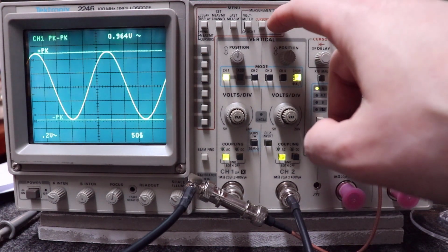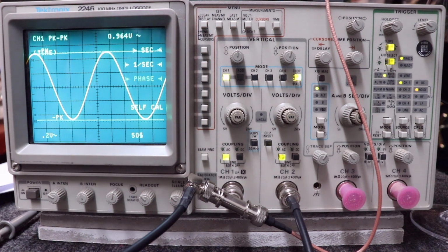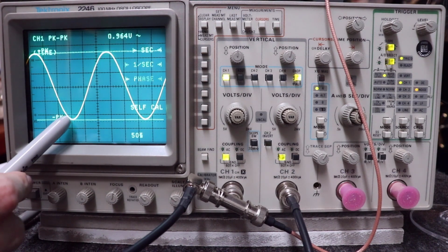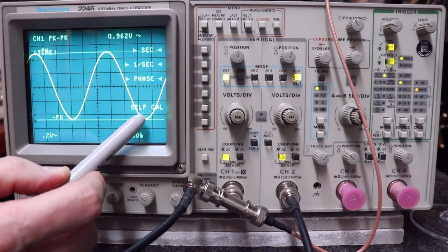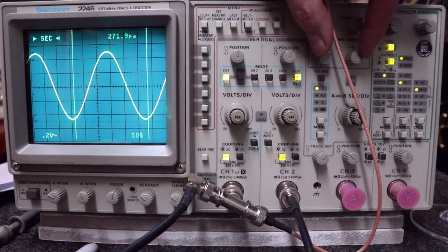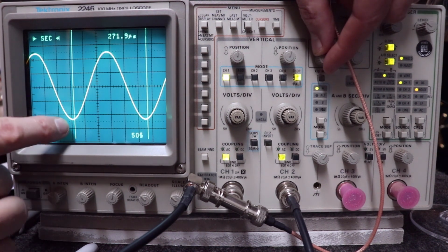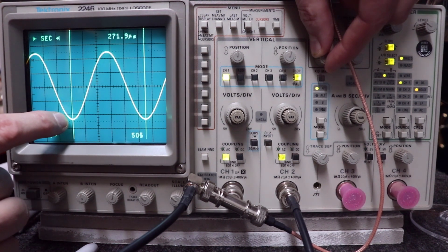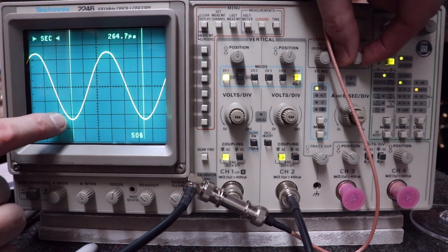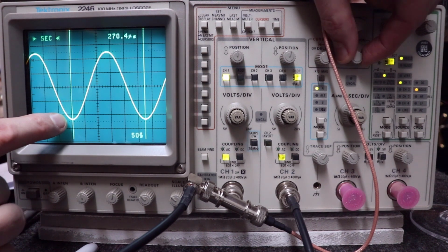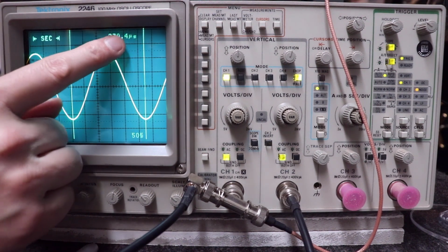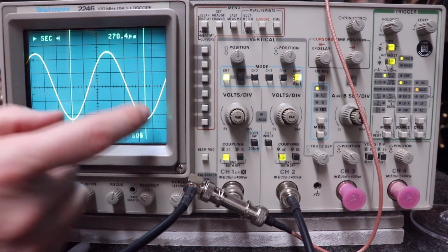Up next here, you can do a time measurement, okay? And if you'll remember, time would be how long does it take this signal to maybe go from this point right here to this point right here. So I could push this button here for seconds, and this is where these two knobs right here come into play. The one on the left will adjust over here, and you get it in the middle of your peak right here. And then the one on the right will measure the distance between, and then you kind of get it on the next peak over here. And what is it telling you right here? 270.4 microseconds in between these two lines.